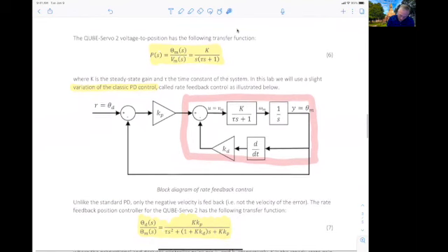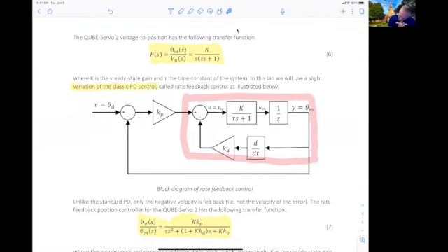And what we worked on in the previous two labs is a transfer function between output theta and input voltage to the motor, Vm. Okay, so Vm is the thing that we're using to control the motor. We change the voltage to the motor and the motor spins.